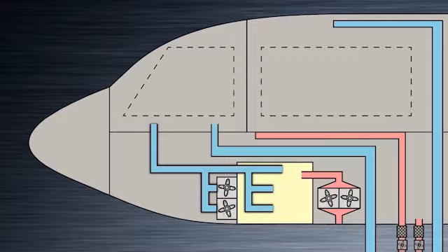You've probably seen something similar in a PC or laptop, with fans that draw air across the internal components simply to cool it down. Although this system is more complex than that, it's the same general idea. Essentially, the equipment cooling system is simply made up of an air supply system that takes cool air to the electronic equipment, and an air exhaust system that removes the warm air. As a protection mechanism, both the supply and exhaust systems contain two fans respectively, a normal and alternate fan.